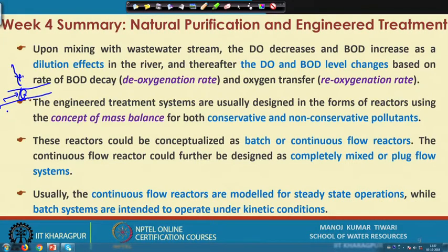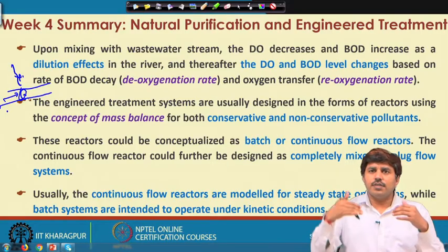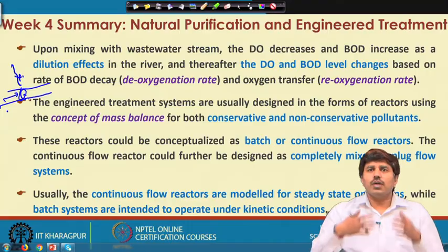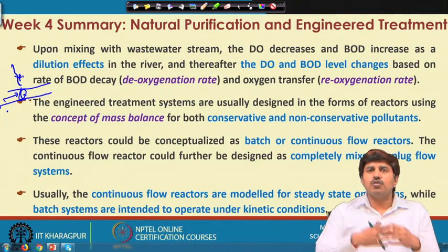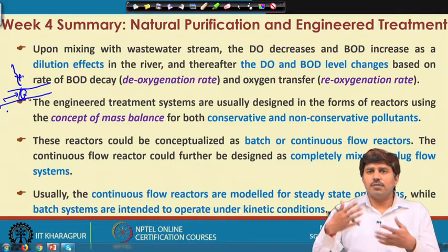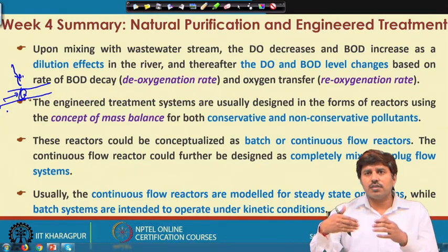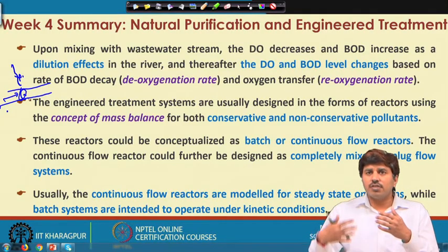in the case of dissolved oxygen, the dissolved oxygen is consumed in the action of the BOD decay. While microorganisms are degrading organic matter, they consume dissolved oxygen, and some is also consumed in the respiration process. That makes the oxygen level decrease, but at the same time reoxygenation takes place.